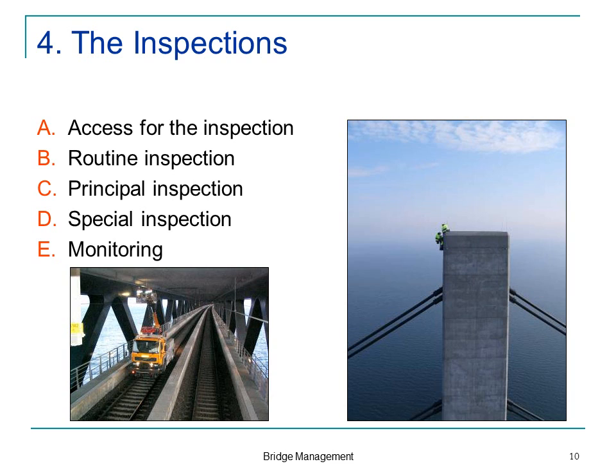Two simple examples here from the bridge. Here we are inspecting the lower side of the bridge deck. For the upper bridge deck, you see no trouble about the access. We have a train which runs in here with a lift on, and it's easy to access. It's easy for us. It's not easy for the people with the railway, because once you place a train here, they can only use one track. This means you cut the railway traffic by 50% at least in that time, if not more.